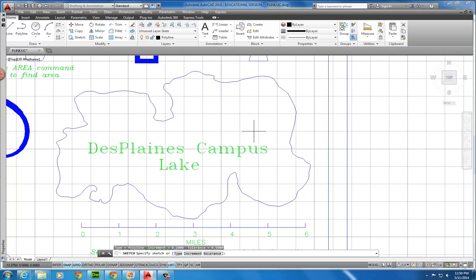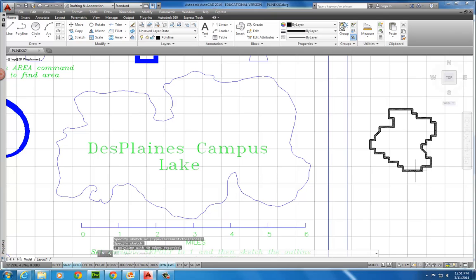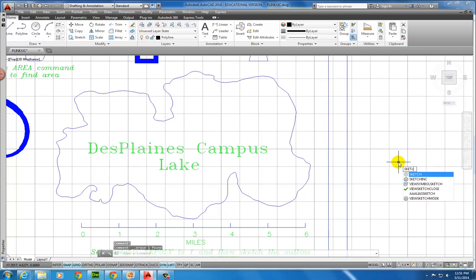And so if I enter sketch and I start to click and put down my sketch lines, it kind of looks like that old Atari type gaming where I have a very low resolution line weight. And so I'm going to modify the increment sketch, and what I'll do is I will type I for increment.